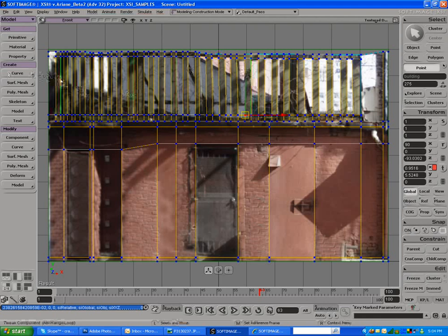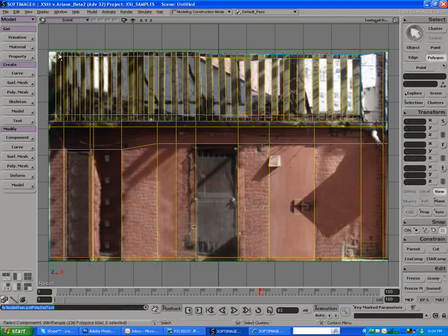Okay, so we're going to extrude those faces. So U is select by ray casting. It's kind of a pain here to select them all, but we'll do it anyway. Just hold, and we'll just go in and start picking these. If you pick something wrong, just Control, we'll toggle it. I can't control my mouse.